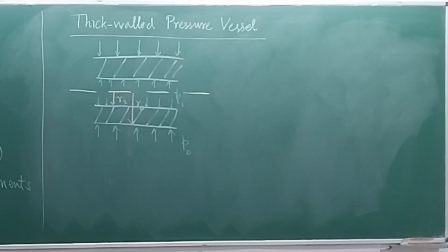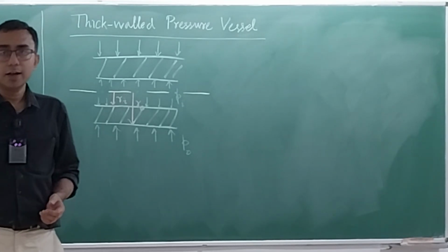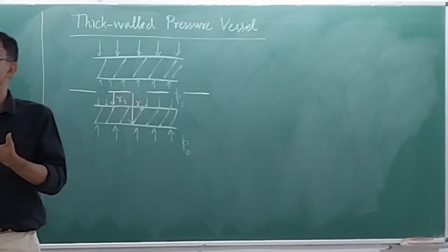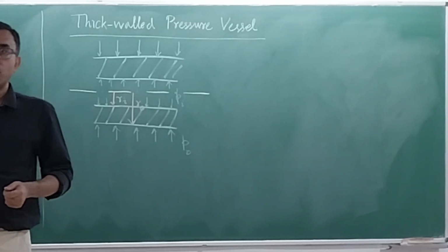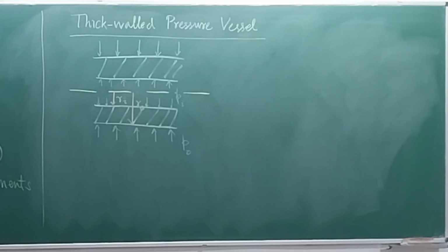Now when I was your age, I always used to get confused between plane stress and plane strain. Which one is what? A very easy, functionally operable way of remembering what situation you are dealing with is to think of it like this: if you have a thin plate which is loaded in its own plane, that is a case of plane stress.